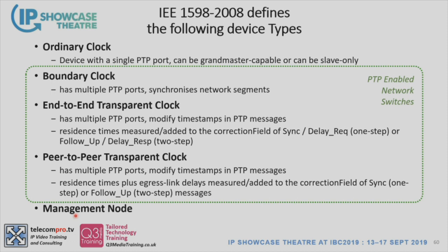It's very important that if you've got a camera, you tell it that you are only ever going to be a slave. The underlying PTP libraries, if they've been implemented just by taking a standard set of libraries, might have the ability to become a master, and you don't really want that. You don't want the master accidentally handing over to something it shouldn't be.